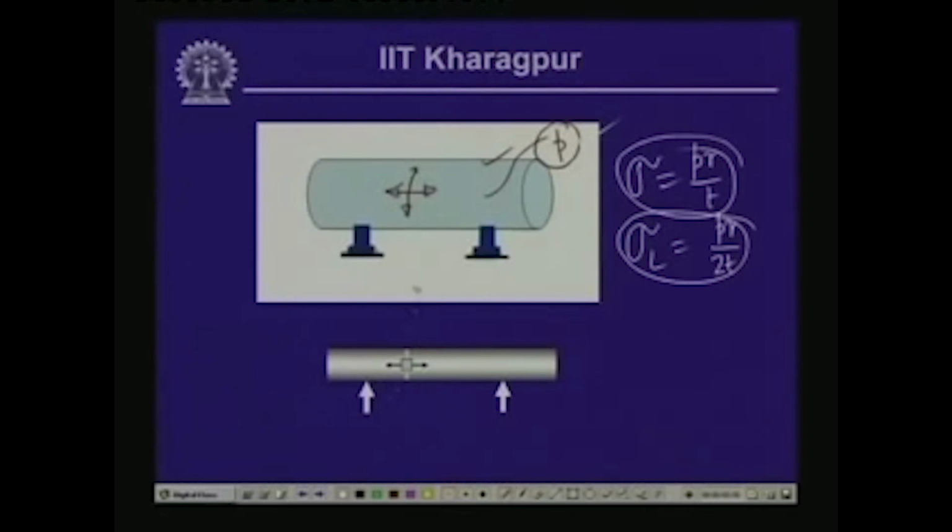Now, if you look into that, this particular pressure vessel is supported at this particular point and at this particular point. Now, naturally because of its own weight along with the liquid, it will undergo bending over this particular part, and because of this bending there will be stresses generated in this pressure vessel. So, apart from the stresses which we get from the internal pressure, we will have the stresses generated because of this supporting point. As a beam, it is getting supported at these 2 points, and thereby there will be deflection of the member and there will be stresses generated.